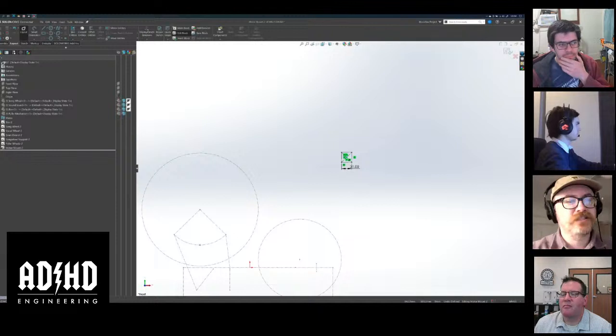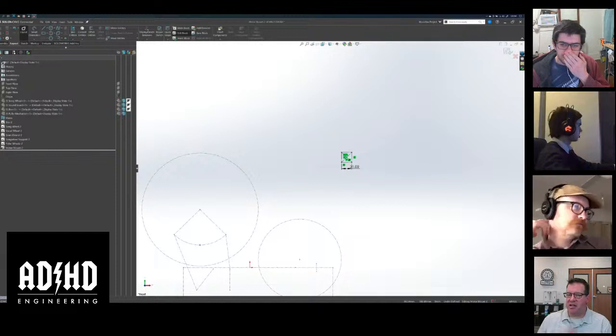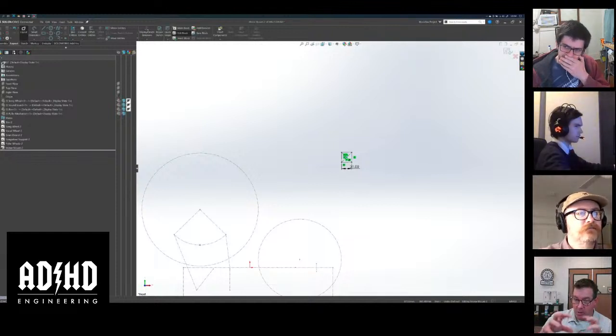I actually don't want to define it while it's a block. I want to define it when it's apart and being mated. But each block, when it's in the assembly, there's a separate parameter outside of the block saying where this block is located, right? So the fact that you have fully constrained the block within its own context shouldn't matter. Once you exit that block, you should be able to move it around in the assembly, I would guess.